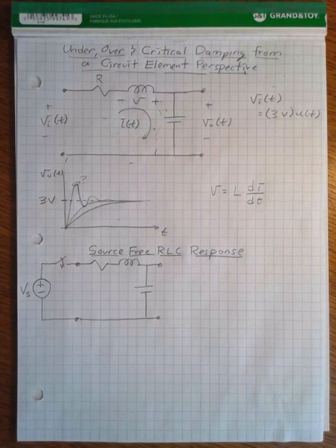Okay, so the next thing I want to do is look at the source-free RLC response. And again, the source-free response is when we switch in a voltage supply, which is modeled as a step function, and we let a lot of time pass, so all of our voltage levels converge to steady state values. And then the source-free response is when we disconnect or switch off that input supply and switch our input voltage back to 0.